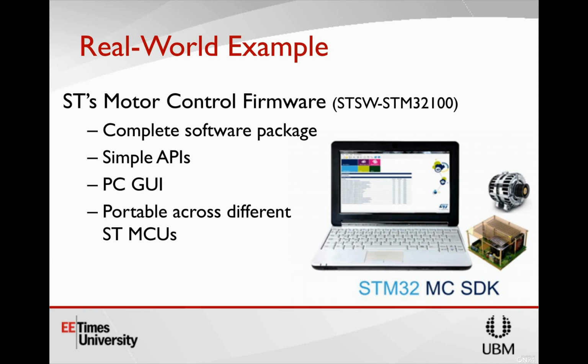Typically it's a non-inverting difference amplifier that's used to convert the current flowing through that sense resistor into an ADC voltage. It's not shown on this diagram because it's a well-known op-amp circuit. I just wanted to highlight what the hardware tends to look like and some of the considerations on when you can actually do the sensing of that motor phase current.